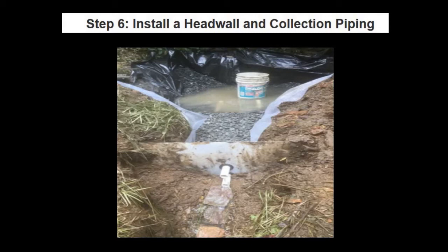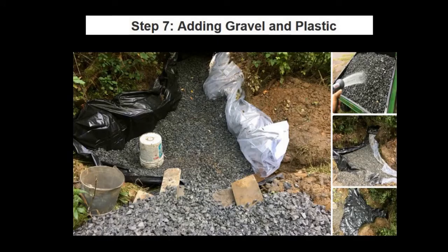In this case, it was a piece of plastic, and they put a bung in to seal where the pipe comes out. In this case, they had 2 pipes. One, I would assume, is going to be their source that provides their water for their uses, and then the upper one would be an overflow so that this thing, when it's buried, wouldn't be floating out of the ground. So you're going to add the gravel and the plastic like we talked about, and this again would be rinsed gravel, which you would either rinse yourself or you can buy drain rock that's rinsed.